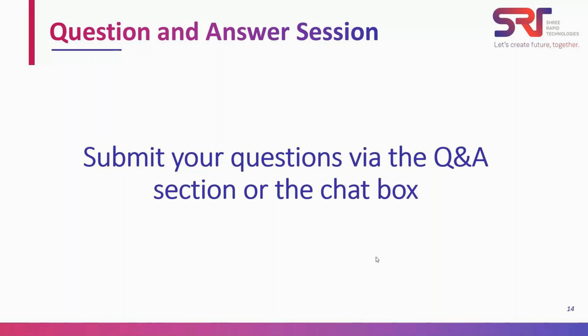Okay, the next question is: 90 micron is the native pixel size. Is there a dynamic pixel size? We do not have a dynamic pixel size, and we do not use pixel shifting, but we do use our grayscaling to produce more than adequate results. In fact, you could see the results. Very little aliasing, very little stepping effect, and fantastic down-facing surfaces.